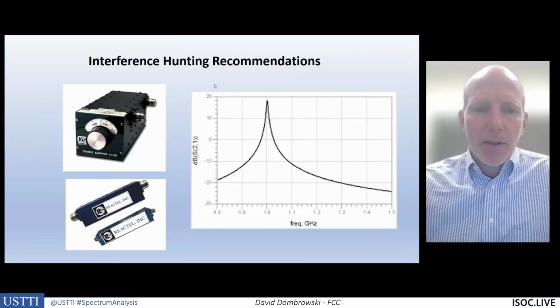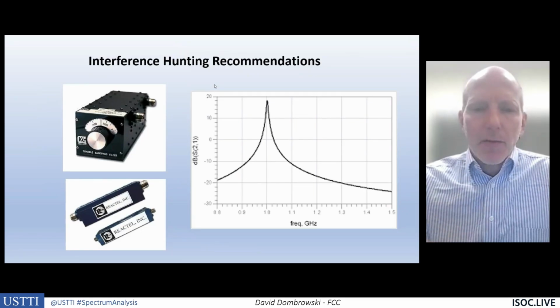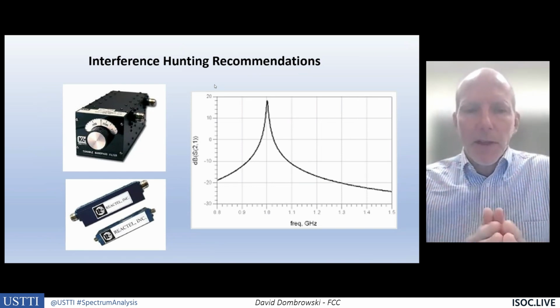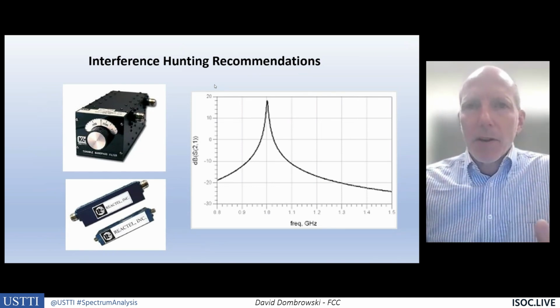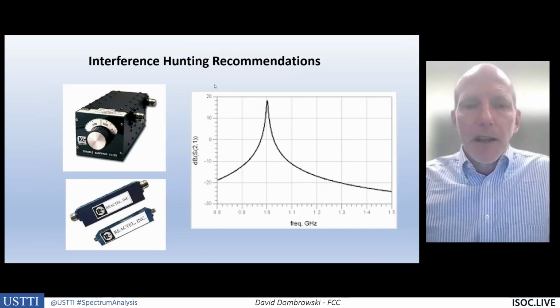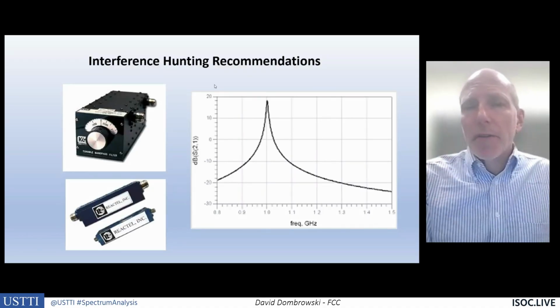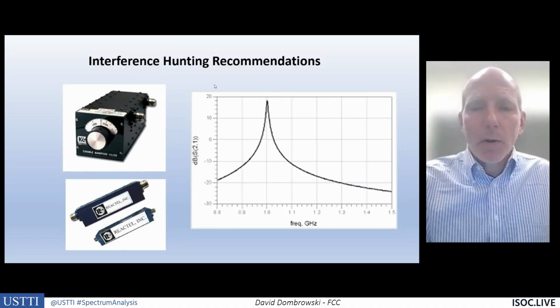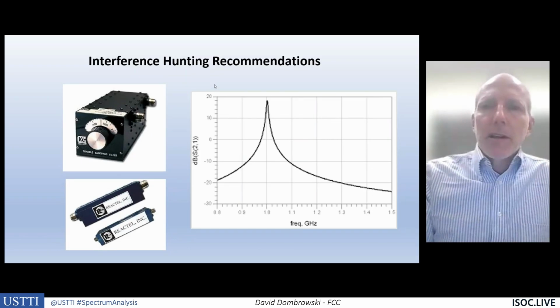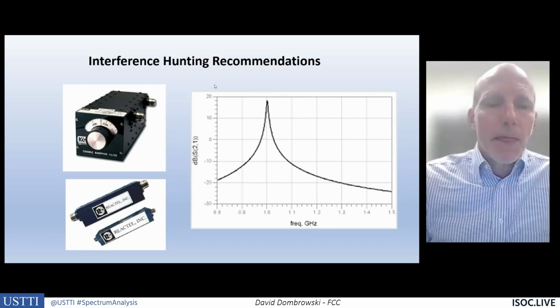Filters have a specific bandwidth. You could buy filters that are very small and light, and they're very frequency specific. And so you go to a manufacturer, say, hey, I want a filter that has 50 megahertz of bandwidth. It attenuates anything outside that bandwidth by 50 dB or greater. Or you can have one that's a very narrow bandwidth, such as one for land mobile radio, where the channel is only 12.5 kilohertz wide or 6.25, and you want a very narrow filter so you don't cause adjacent channel interference or receive adjacent channel interference.